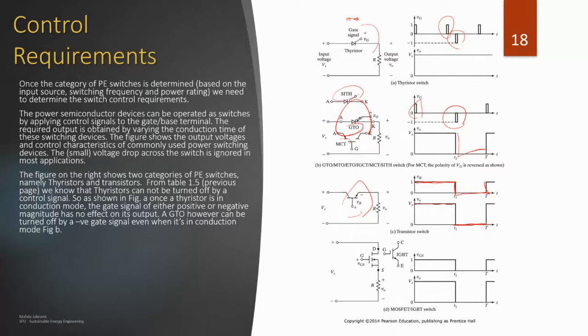That means that your control system will require more power. It'll consume more power because it needs to maintain the signal rather than just the pulse, right? So if you're using this switch for a tiny electronic pen, if you like, that has a small battery in it, this wouldn't be the right choice because it can deplete the battery really fast. You need something that only creates a pulse, and that's it. So that the control system doesn't consume that much power.